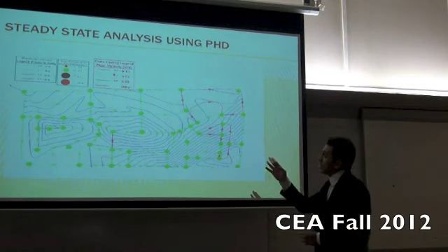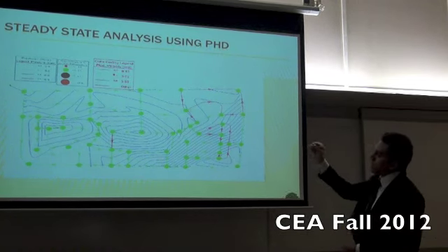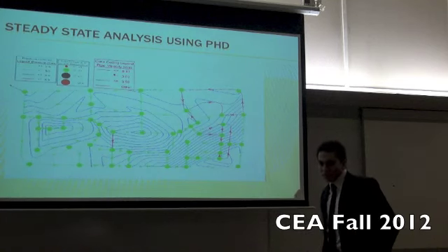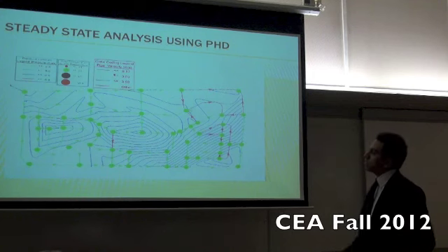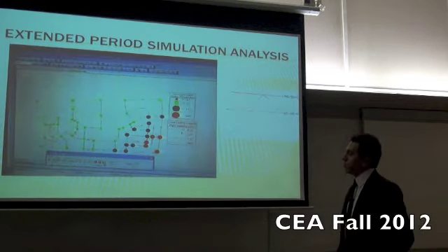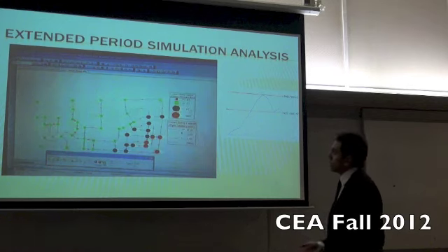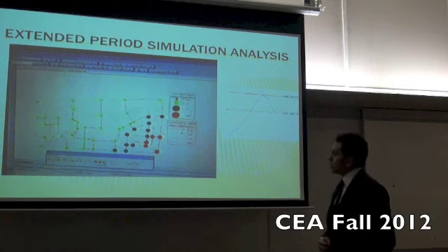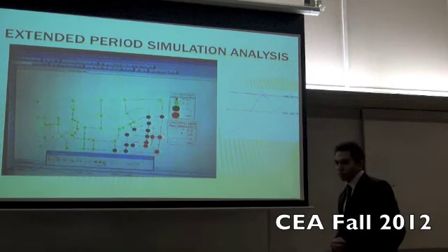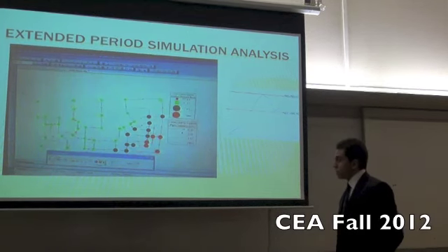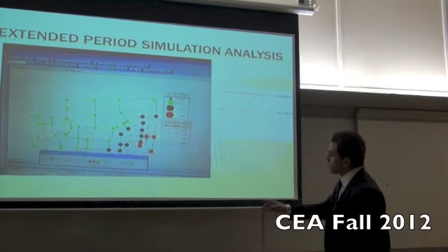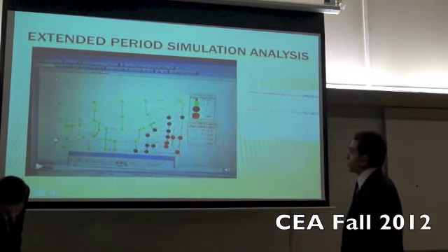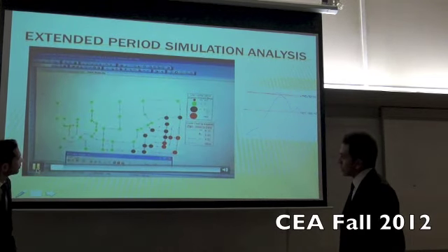Okay, this is for the steady state analysis, which analyzes the system on the peak hourly demand, using the maximum flow. Another analysis is the extended period simulation analysis. It analyzes the system over the 24 hours, and gives us the pressures at different times.